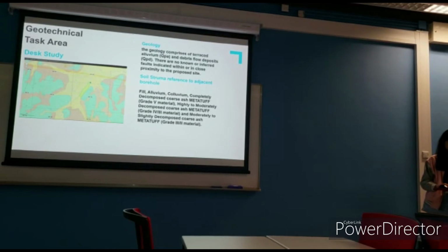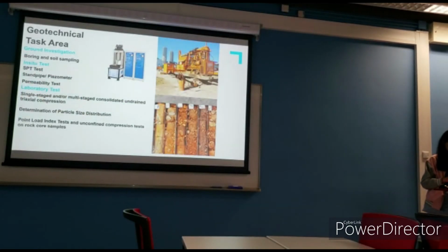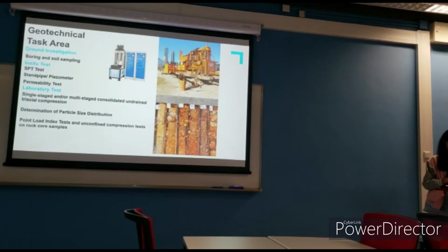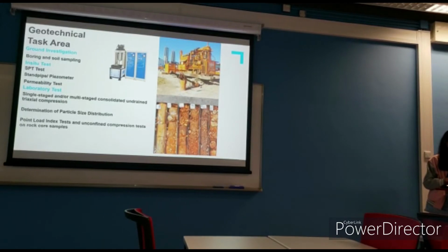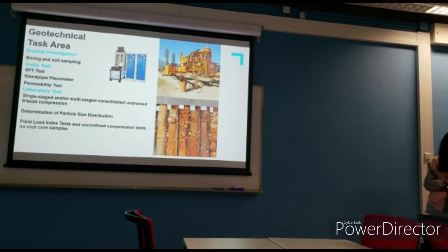We can see that all the materials are sandy in nature. For more precise practice for design purpose, it is recommended to carry out the ground investigation by boring test. A vertical borehole should be sunk into the proposed site to obtain the soil sample. Also, in situ tests should be carried out, such as standard penetration tests, to obtain the soil layer in order to estimate the relative soil density and soil strength for design purpose.